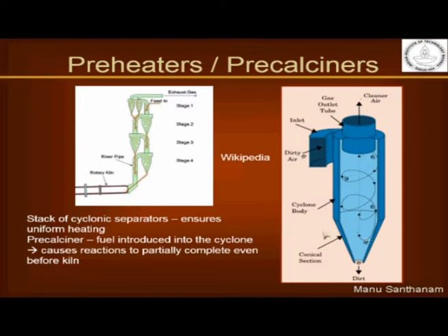So the same principle is adopted in a preheater tower cyclonic separator, in which you put in the feed, and what it simply does is it has a cyclonic motion with which the powder, actually the mixed powder, goes into this preheater, and the heat that is generated in the preheater is getting rid of all the moisture that is present inside the raw material. Now in this cyclonic process, when this mixture is inside the cyclonic preheater, there is also a much better mixing that is taking place, and ultimately all the material then comes out and goes into the rotary kiln, which is at the end of this preheater tower.